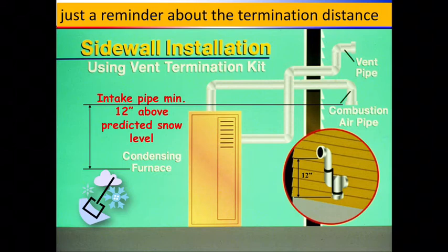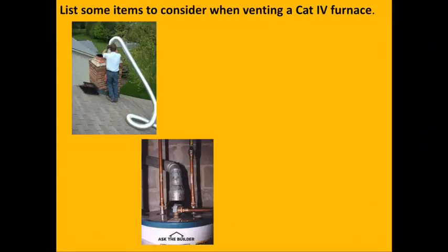Usually the exhaust pipe is not the one that's going to create the problem. It's more the intake pipe that'll either get full of snow or it'll plug up and it'll stop the unit from operating. So be careful with that.